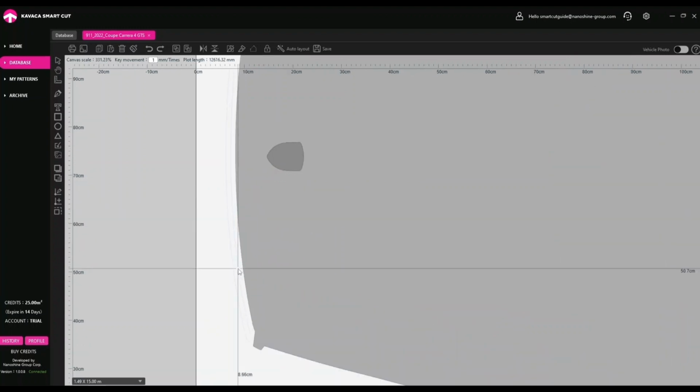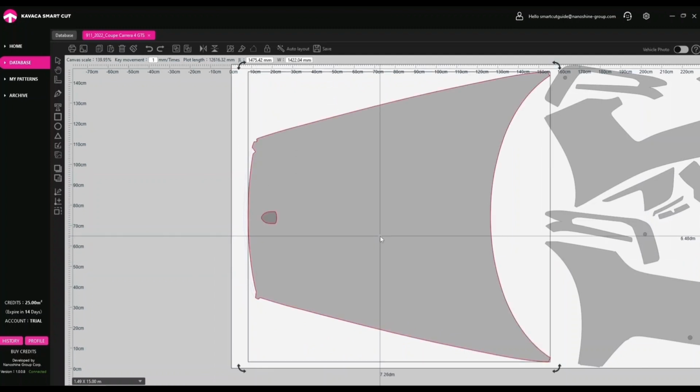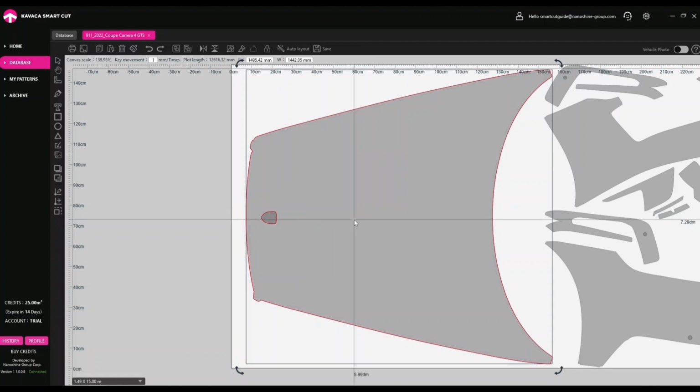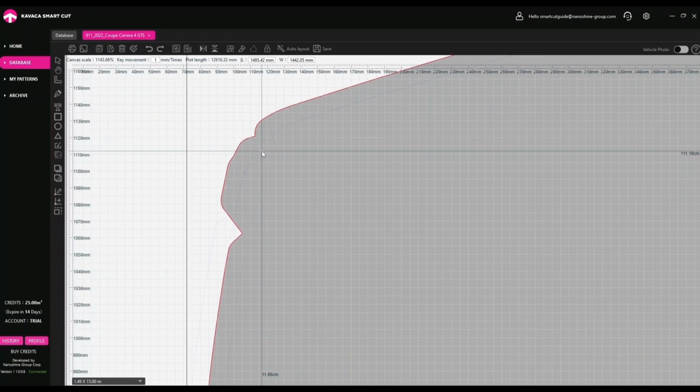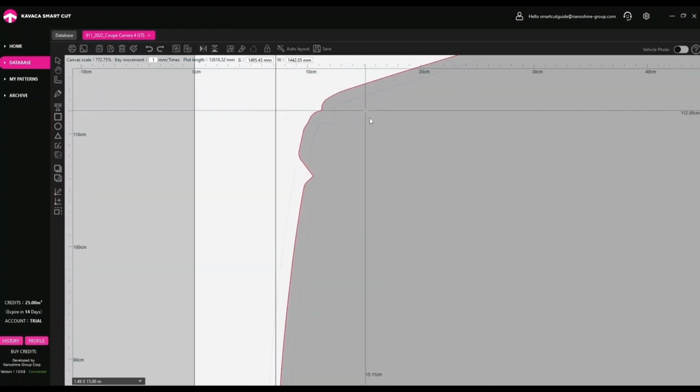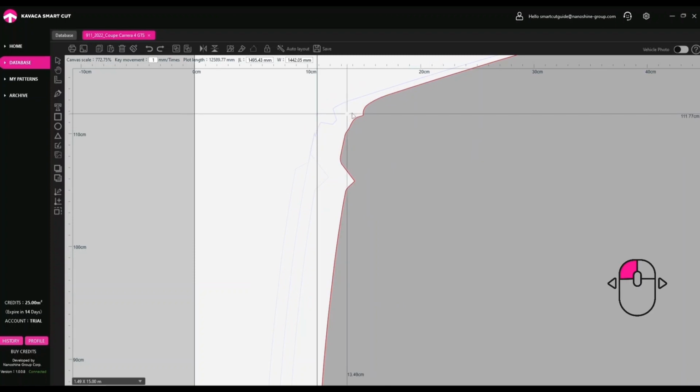By selecting the entire pattern without highlighting certain points, using this function will increase or decrease the size of the entire pattern on all sides at once, at the same time as the edge length is changed. A blue line shadow of the original pattern is automatically created, so that you can clearly see the change in pattern shapes. You will clearly see it by dragging the pattern aside.